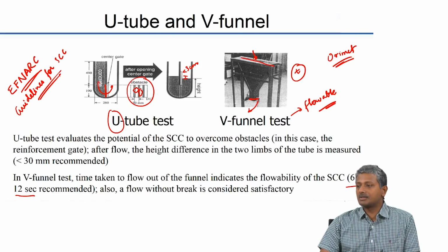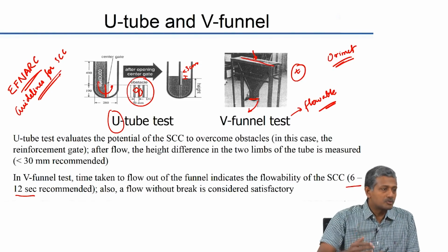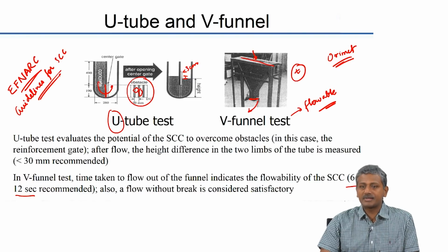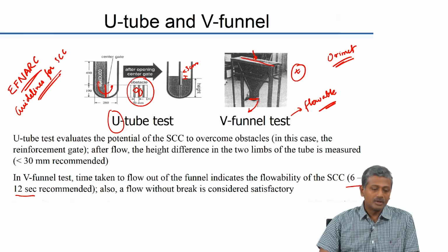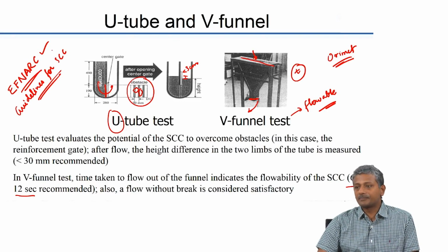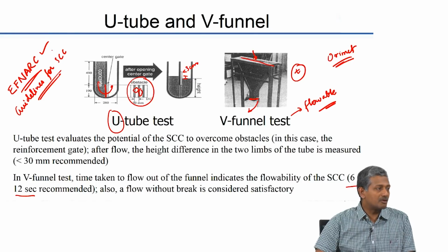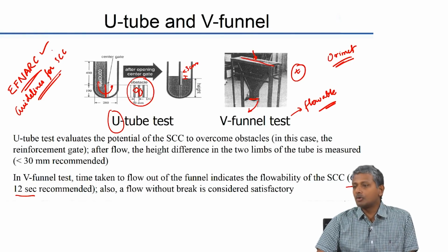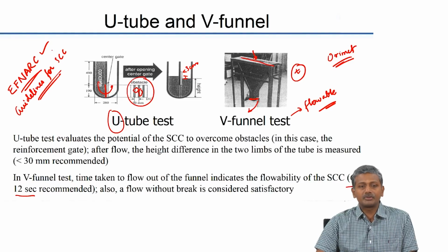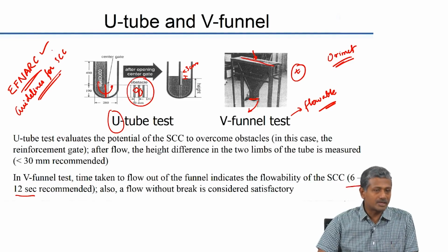The design of the concrete is not yet standardized, or there is no guideline published by the standards organization or concrete institutes in different countries for the design of these special types of concretes. So, for design, the best strategy is to still use the guidelines for SCC which are given by EFNARC. I think the last version came out in 2005. Beyond that, there is no real change in the methodology of design of SCC.